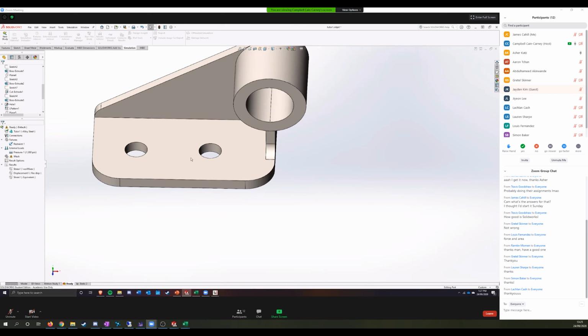So the force will be high in that spot. Because in reality, if you've got a bolt going through this hole, it can translate vertically up and down the bolt, right? But you fix it so it can't. So the fixture that you've applied to it is not representative of a real situation. Yeah, okay. So that's why you're getting an excessive stress around the bolt hole.